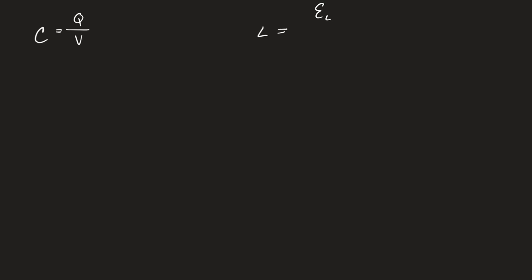Now, the other side of that, what causes the EMF is a change in current. So we relate it to current. So when you apply current to a system, that change in current causes a change in flux. The back EMF you receive is proportional to the change in current. So a larger change in current should produce a larger back EMF for the same inductance.